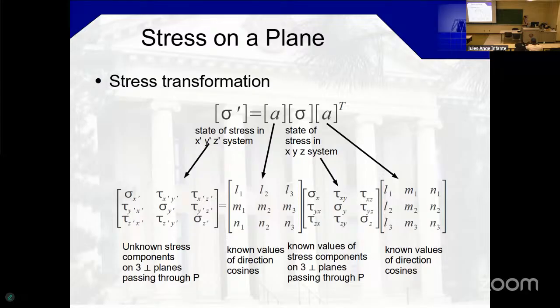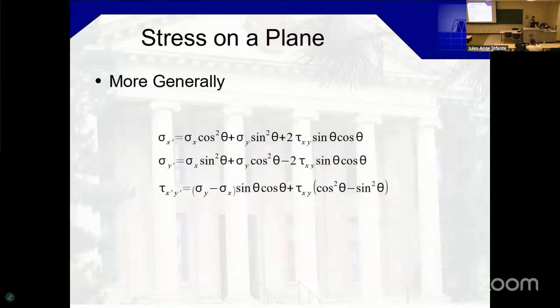And it's because of those transformations that when we want to find the stress acting on another set of coordinate systems, we have a matrix that represents the stresses acting on one set of axes. If I want to express the same matrix on another set of axes, I have to take my cosine matrix, which contains basically my rotations. But it's not just the rotation. I have here the transpose of the rotation, because of these combinations.